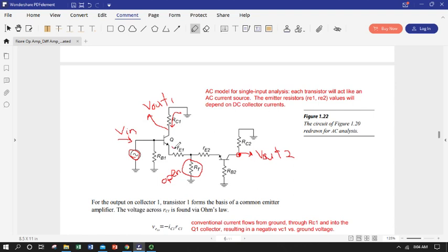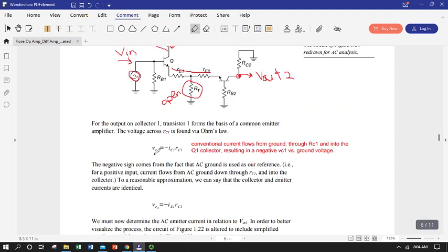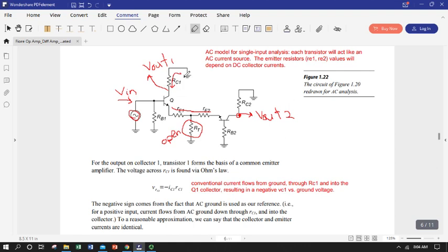So our emitter current coming out of our first BJT is going to flow through RE1. It can't go through RT because we're going to assume that's so big it might as well be an open, and it's going to flow through RE2, and then we're going to refer to a different AC circuit schematic to see what happens after that, because this one doesn't show it too clearly. But before we skip to that, we'll just focus on our collector currents and voltages.